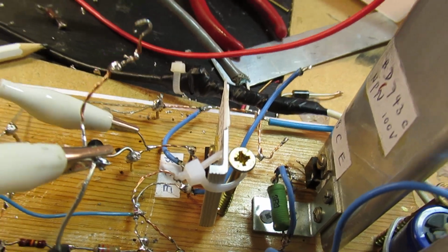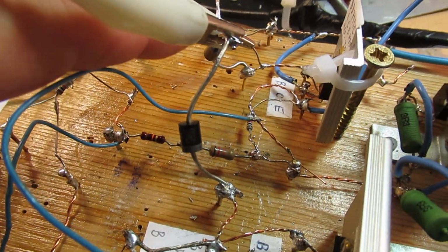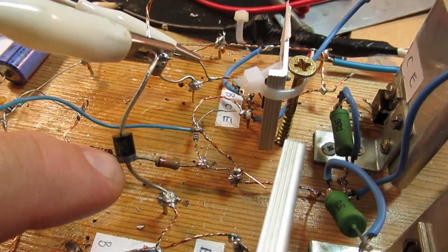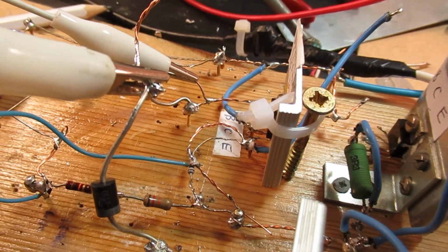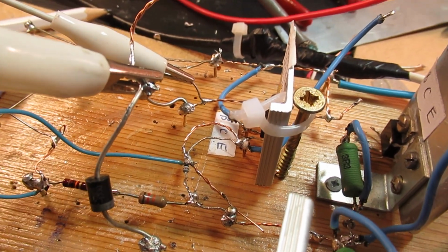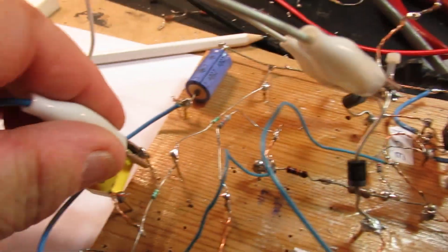And we know there's often a kind of trick: mount these two diodes, which are responsible for the quiescent current, on the heatsink so that they are heated up. That sometimes can help. Anyway, take away the audio signal again. Put on the audio signal again.